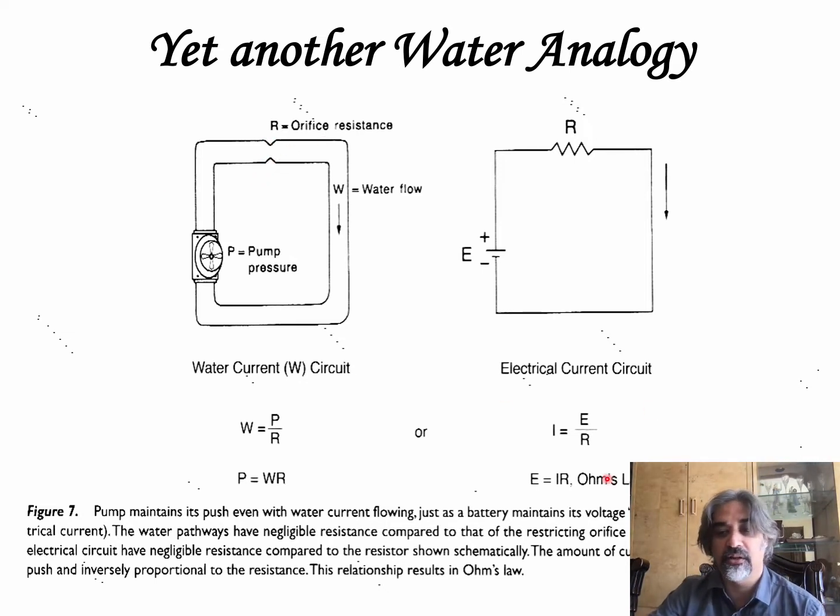A series circuit occurs when there's only one pathway for current to flow. Each resistor adds to the overall resistance. Equal currents flow through each resistor, while the voltage drop across each resistor depends on the individual resistances. A parallel circuit contains branch points where voltage is equal across each resistor. Parallel resistances are calculated such that the overall resistance is always less than that of any single branch's resistance in the circuit. This derivation is not going to be reviewed here, and it's really not relevant, but I just wanted to remind you about series versus parallel.